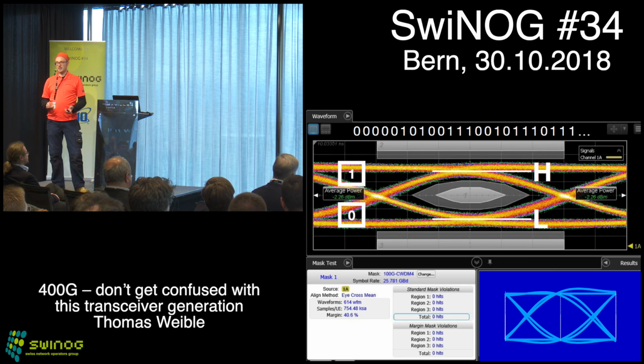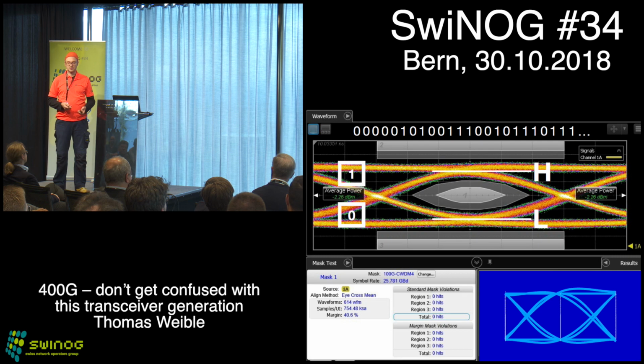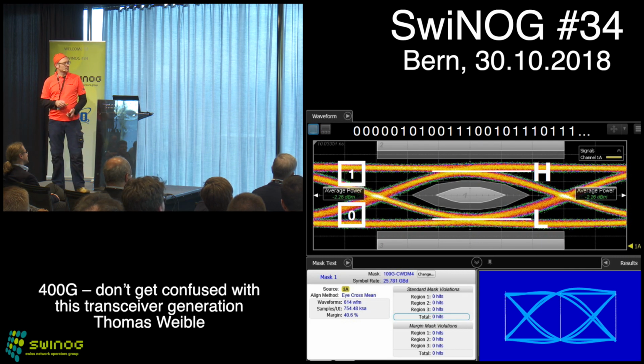We are talking about high-speed signals in a frequency of 25 gigahertz, and the rectangle doesn't exist any longer, so it's more that sinus, just due to the fact of that high speed. And so we have 2 events, high and low, representing one single bit. What makes an eye diagram is basically that shape in the middle, and that's a really important one.